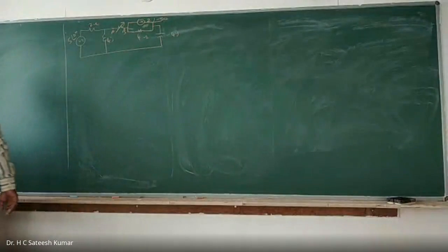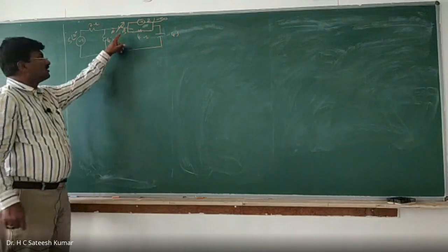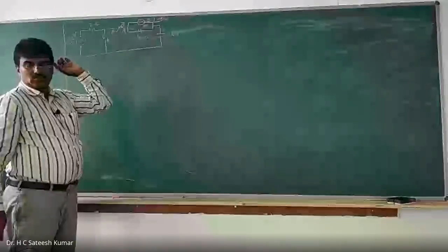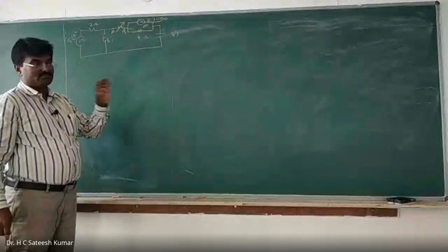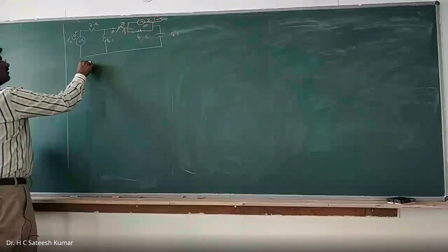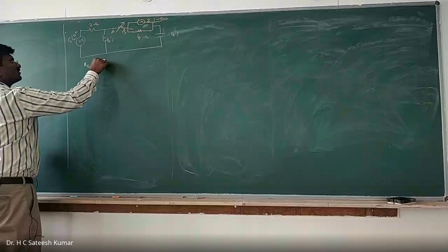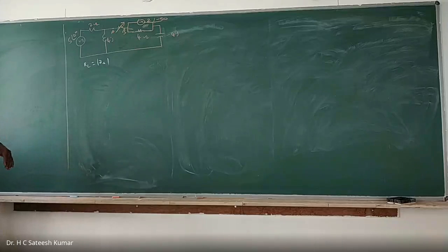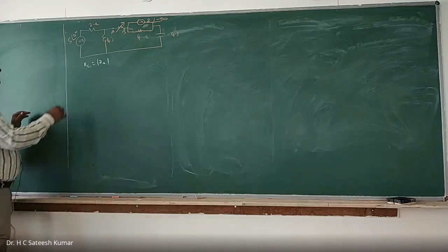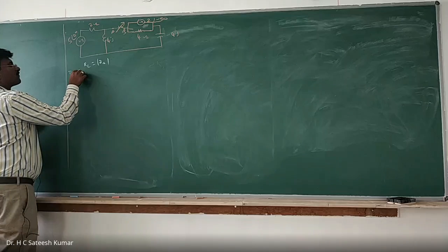Okay. You see this question. When you see this question, the load is a pure resistance and source is having impedance. So therefore it belongs to the second case. The condition we should use is ZL, RL, is equal to the magnitude of ZS. This is the condition we should use, and then we'll have to go for the power. We should do this problem carefully. Small twists will be there in this question. First, as usual, you find out VTH.